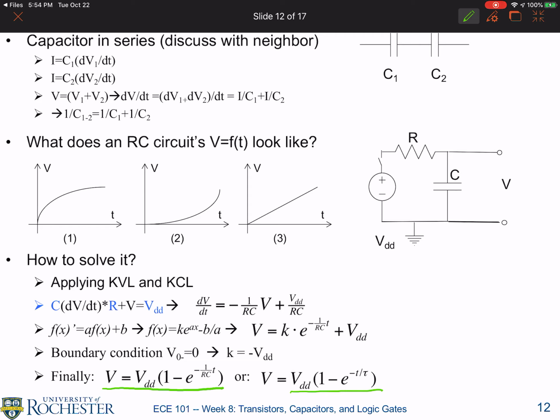Sometimes you hear the term the RC constant because it's literally the value of R times C. So if you look at the units, the resistor unit ohm times the capacitor's unit farad, it's in fact that of time. So an exponential function like this can be drawn like that, and you can remember some factor that in 1 tau you will decay by a factor of e.